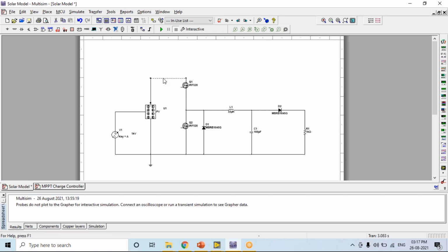Right, so MOSFET control is not the same as how we control the MOSFET of your inverter. Actually, in the inverter we also had to do an extra step, but since it was a simulation I didn't do it. But in this simulation, that should be done. Last time, when we supplied the voltage from LabVIEW to Multisim, to the MOSFET, whatever voltage I gave to your gate was with respect to ground.